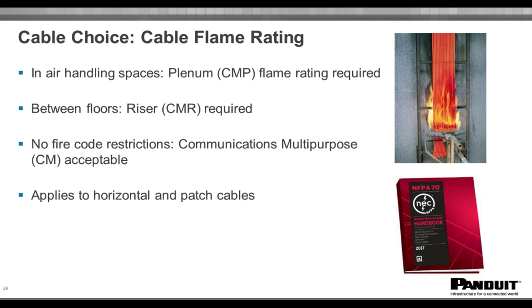And there's also a different type of cable called CM, or Communications Multipurpose, and that's where there are no fire code restrictions. So that is typically what we see for patch cords. But with these cable flame ratings, if you're going to put any type of cable in a plenum space, it must be a plenum. So it applies to horizontal and patch cables.